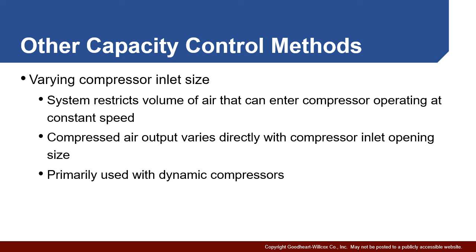But it's far more problematic with positive displacement pumps where you have airtight seals. It's going to generate significant stresses and this option is not particularly energy efficient. It would be problematic with positive displacement pumps. But for non-positive displacement dynamic compressors, this method works relatively well.